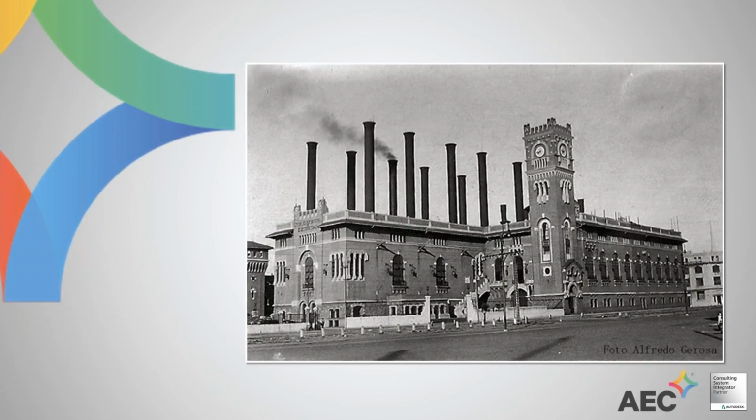Every measurement will take millions of points and we'll assign them an XYZ set of coordinates, and if we have set it to do so, it will also give each point an RGB value, so a red, green, blue value, so it's color. So we're going to have millions of points over a surface, each with their own set of coordinates and their own color. You put all those points together and you will get a representation of that surface.